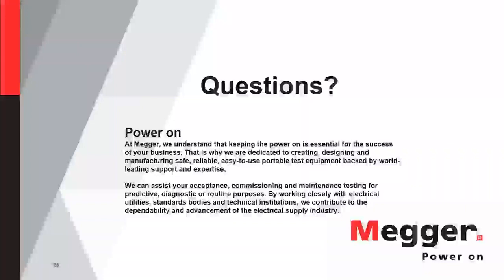As over travel, maybe 5% to a maximum of 10% is pushing it for sure. As you're starting to get over 5%, I would say rebound maybe half that. You can over travel some. As you're starting to rebound, it's a problem as well, especially for vacuum circuit breakers, because now those contacts are touching, and if you rebound, you can have quite an arc there.